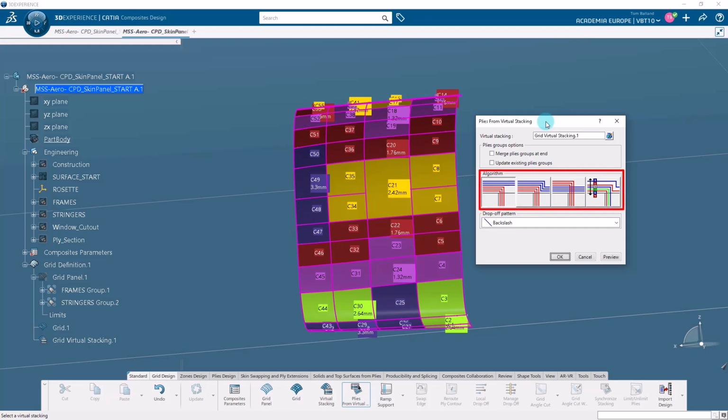Now, you have to select an algorithm to define ply boundaries. There are three main types of algorithms. The minimum crossing method is used to create ply boundaries that avoid crossing ply ramps as much as possible, but may result in ply definitions that are larger than would be produced by the other two algorithms. Then, the minimum crossing and weight-saving method creates ply boundaries that are optimized to balance both the smallest area with the minimum ramp crossings. This algorithm option typically produces the best solution for weight reduction with minimum ramp crossings.